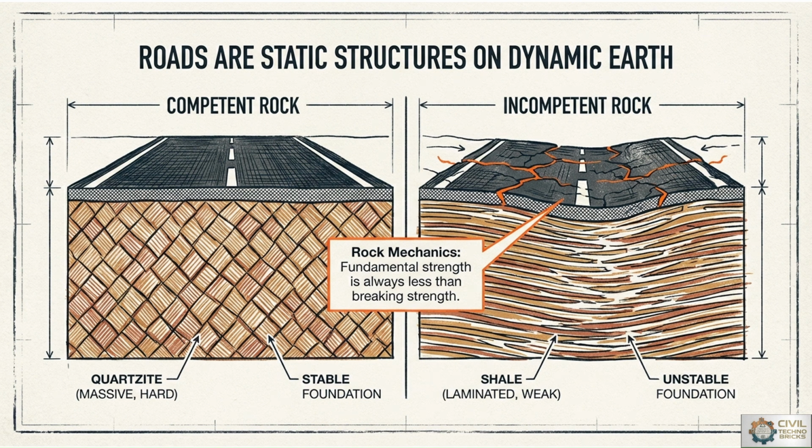The importance of geological investigation in highway projects is that it provides information about subsurface soil and rock conditions along the highway routes. Site investigation helps identify unstable slopes, weak formations, and fault zones too. Proper geological assessment minimizes maintenance cost and construction risk also. Investigation supports safe design of embankments, cuttings, bridges, and retaining structures. Highway planning becomes more efficient when geological hazards are identified early and mitigated.